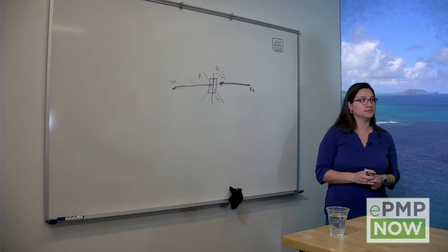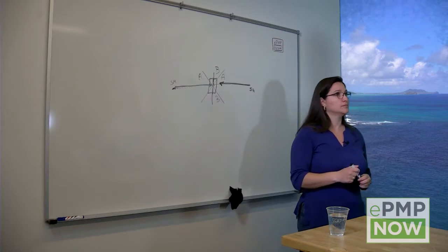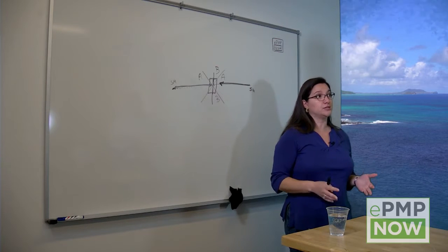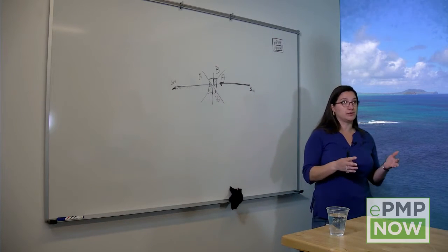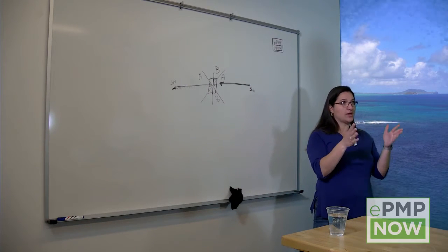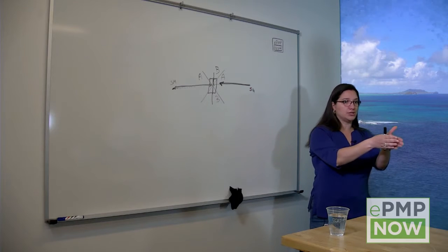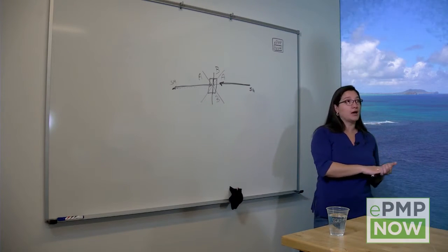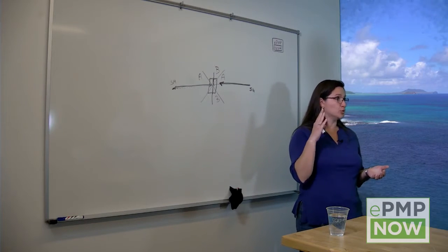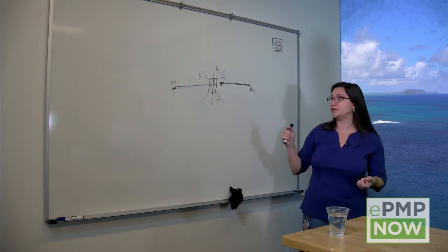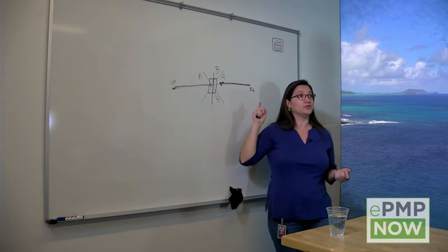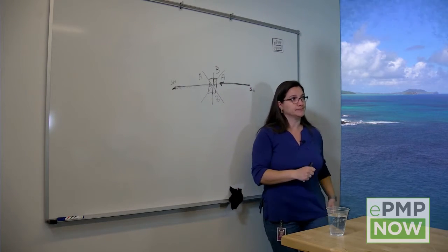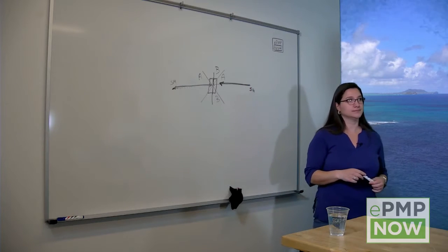So for our sector antenna, what is the front to back ratio? We have more than 30 dB front to back ratio. It's 35 at boresight, meaning if you think of 0 degrees in front and in the back. And this allows you to go up to the highest modulation level because the protection is enough, even if you don't have any additional separation between the antennas. I see. Excellent. Thank you.